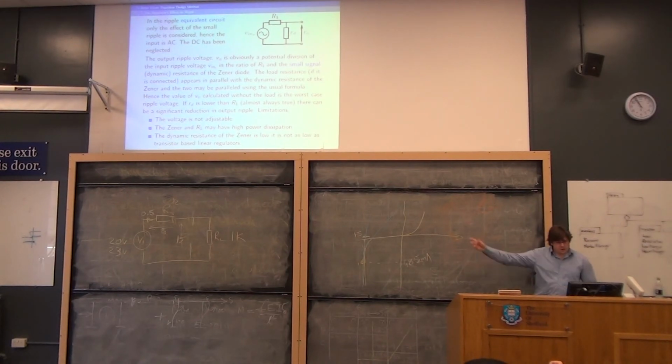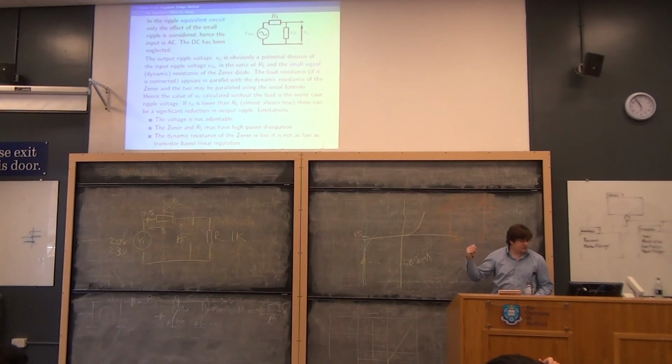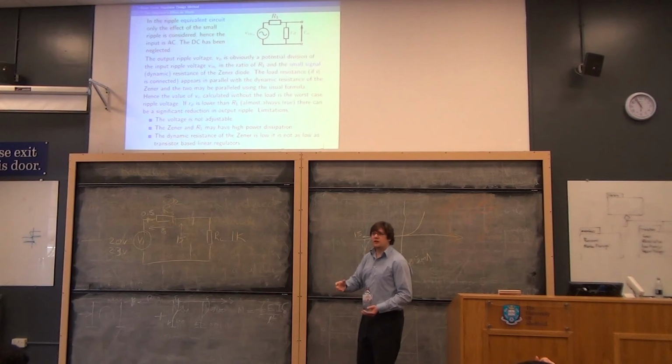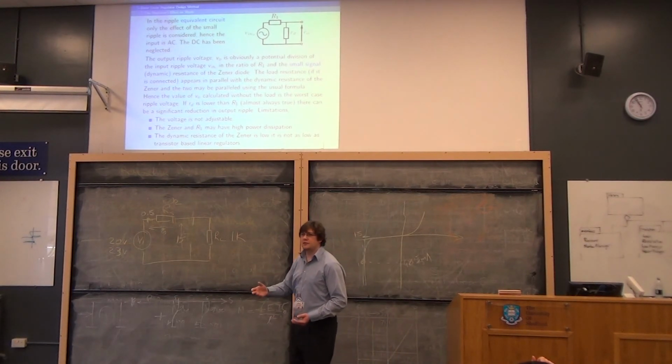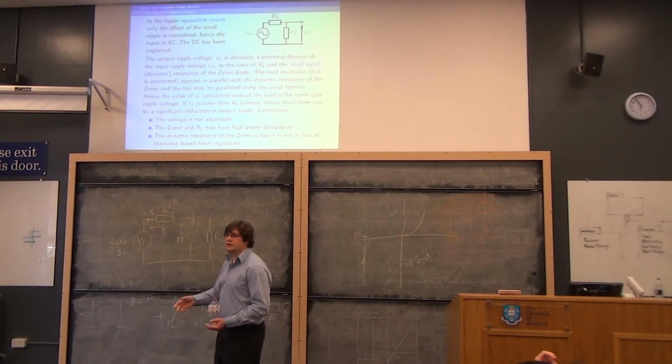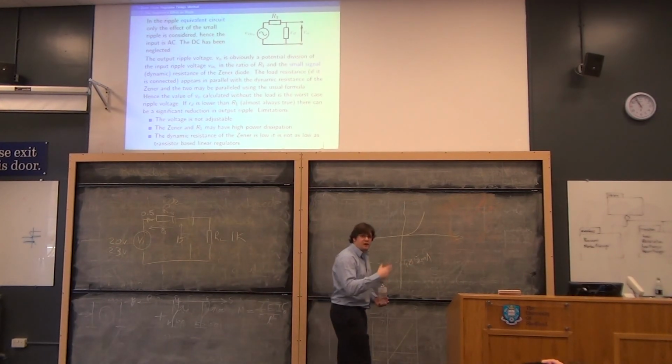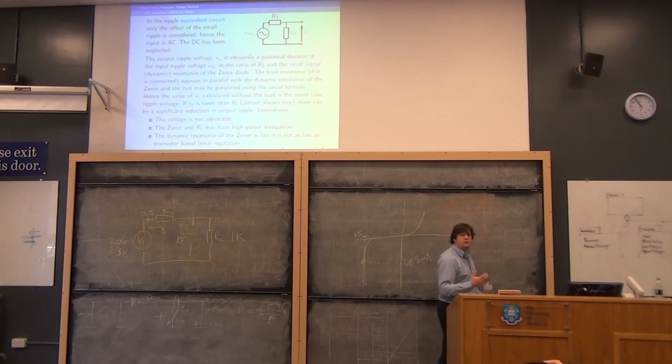So we'll plug in R1, which is RS on the other board, and the value of RD, and then we say, well, what's our ripple? Well, we know what our ripple is because we previously designed a linear power supply to bolt onto this, and we'd have come up with some ripple calculation from the prior lecture. That would be our value of ripple. We just plug in the numbers, and out drops a new value of ripple.